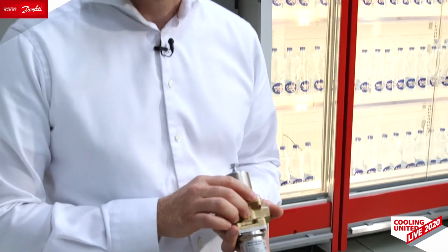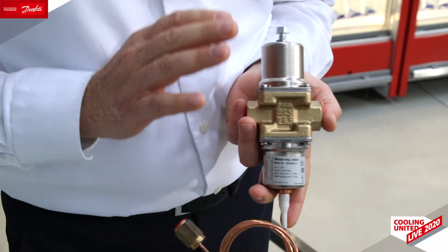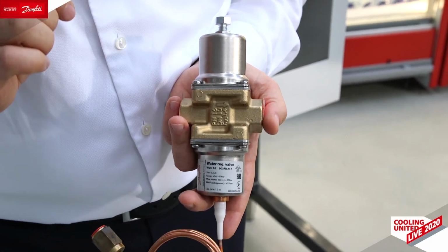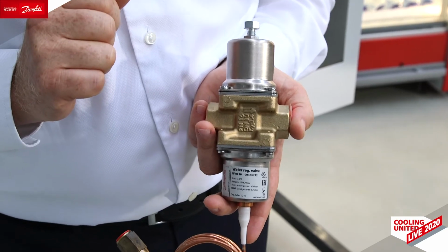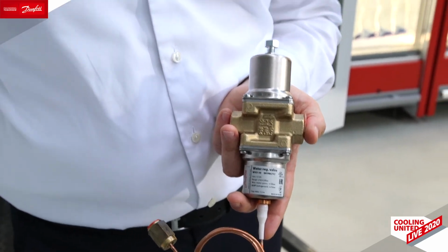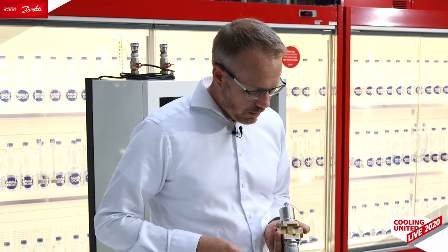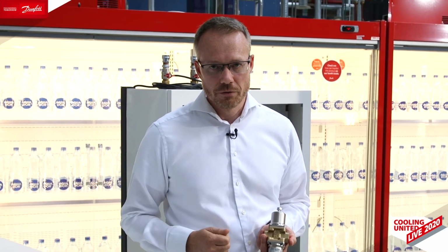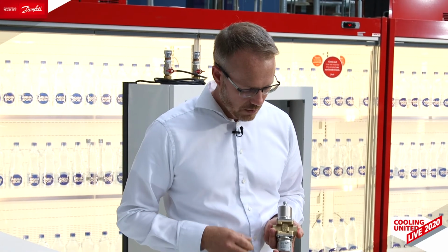In very simple systems, where we don't have a lot of electronic controls, then we can use a purely mechanical control to ensure that the condensing pressure is maintained. So when the ambient temperature, when the temperature outside goes down, and you have low temperature on your water loop, then in some cases you need to make sure that you have enough pressure in the system to drive the refrigerant through the system and the oil through the system.